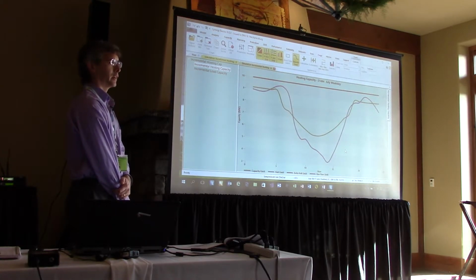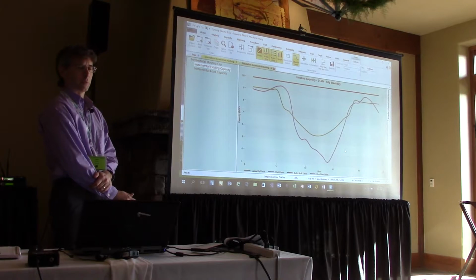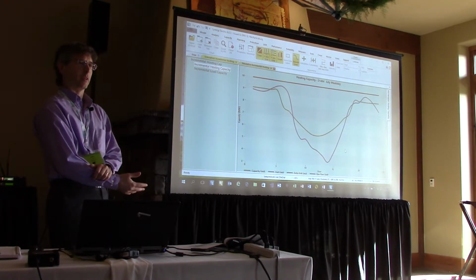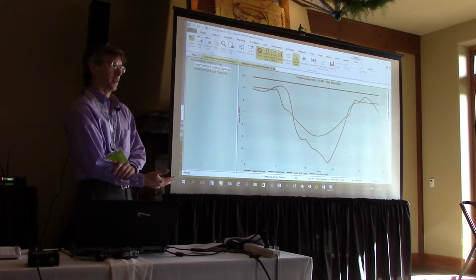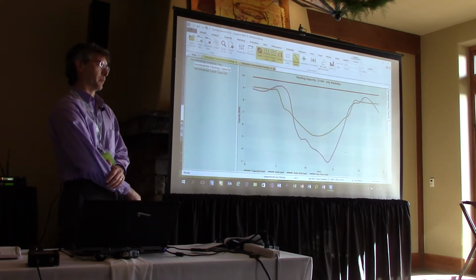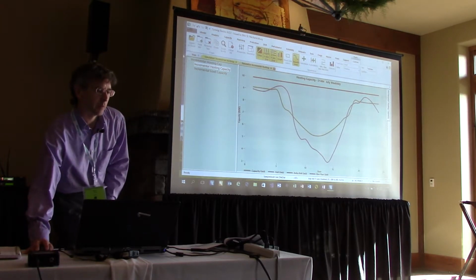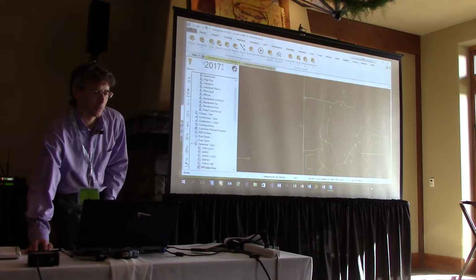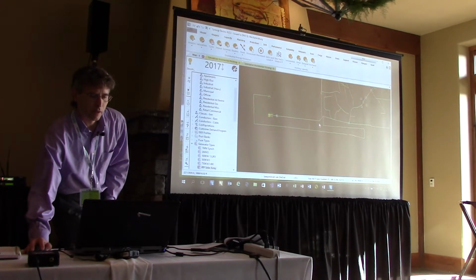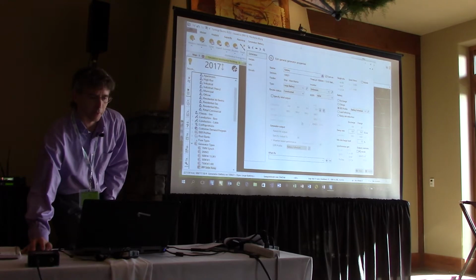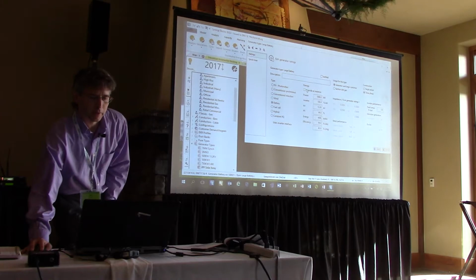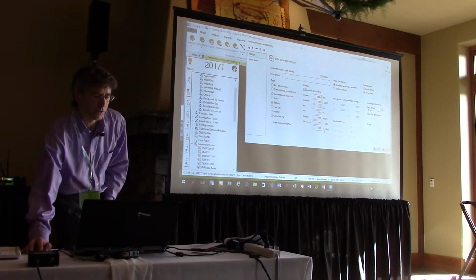Okay, got it, yeah. So Reed's saying that in some situations they have requirements that a customer would be non-exporting during the day and exporting at night, so that they have storage of some sort, right, batteries, and that's a big deal. You probably saw at the time, the single day analysis, we do battery modeling. There's a big one on this model right here that's affecting the hosting capacity. I've got a large battery. It's got a nameplate value of 1 megawatt, I think. Yeah, it's a 1 megawatt battery. We've got efficiencies here for discharging and charging.